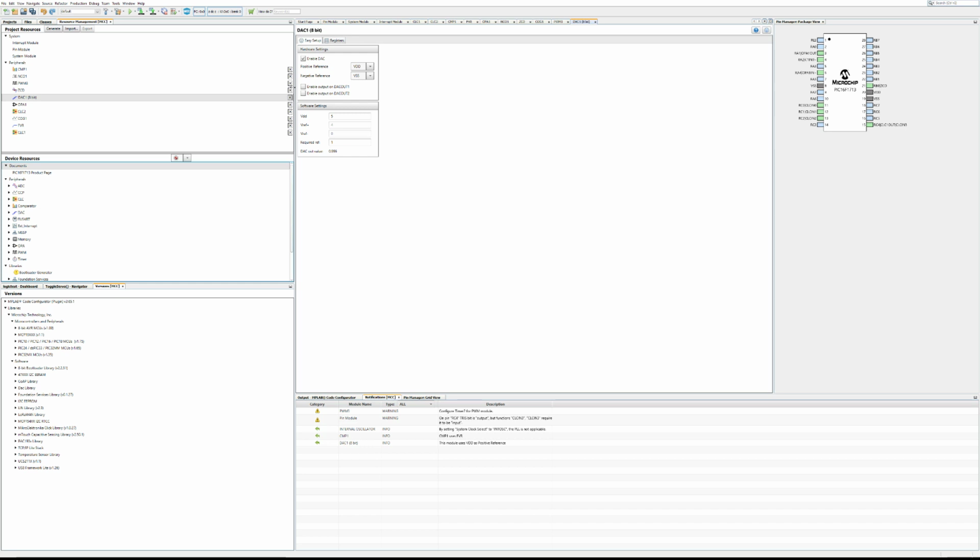You can define this at configuration time and just say, I always want you to output a specific reference voltage, and then you can utilize that in the op amp or the comparator or such. And so you've got an 8-bit DAC and a 5-bit DAC, as well as the 2-bit internal fixed voltage reference, which I believe you can select as a positive reference here. And then you can also buffer these through the op amp if you want to be able to drive loads at 20-25 milliamps, something like that. So yeah, extremely versatile chip.